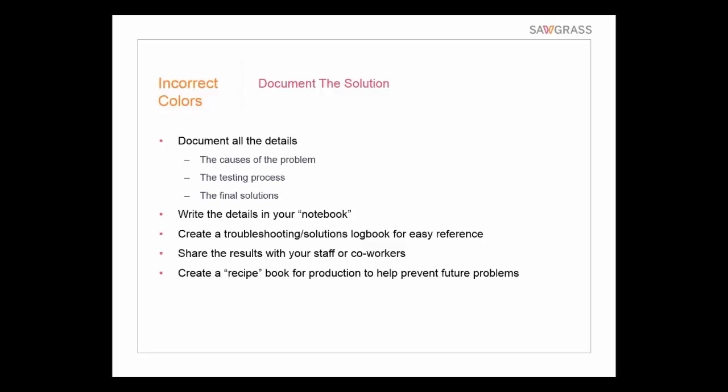I mean, heat presses can get hotter as they go through the day. And what I mean by that is when we're constantly pressing, we have heat that's actually going through into the bottom of the heat press as well, so we may have more heat radiating out as we go. There's other little things, and this comes from that knowledge base. Some people have gone around and start trying to preheat some of the products they're going to press, and that is not something you want to do with sublimation.